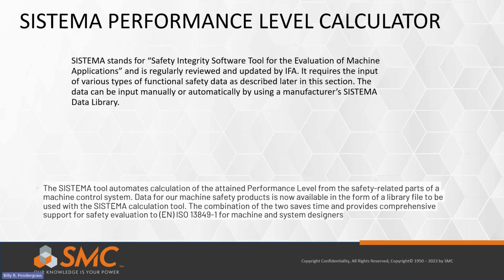ISO 13849-1 does not use the term SIL. Instead, it uses the term PL, or performance level. In many respects, PL can be related to SIL. There are 5 performance levels. PL a is the lowest and PL e is the highest.